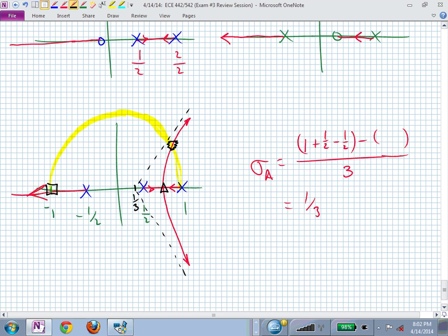That's assuming that that's a very accurate intersection point of the cloud. But you could then say, oh, k of 1.5, you could plug that into your closed loop characteristic equation, evaluate the roots at k equal to 1.5, check their magnitudes, and if they are 1 or less, that's still okay, isn't it, for k? Questions?